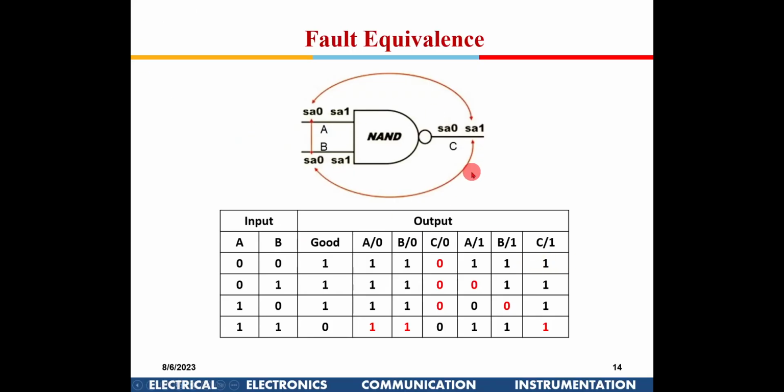So for the NAND gates, these are the faults which can be collapsed. The collapsing will be with respect to the output only. Of these two inputs, you can actually collapse it to one of the nodes. Generally, in equivalence fault collapsing, we move it from the input and put it at the output. That's what the algorithm does. You can retain any one of them. It doesn't matter.